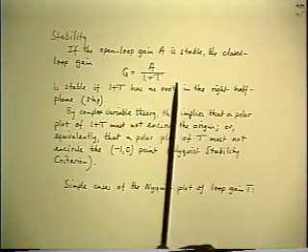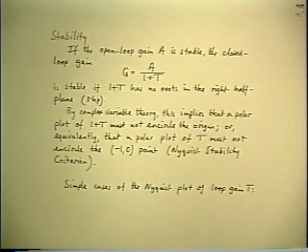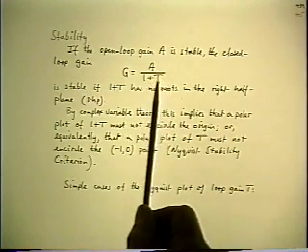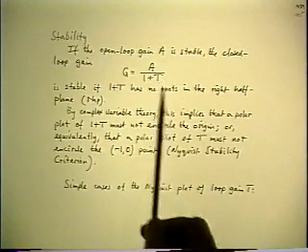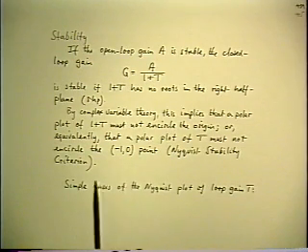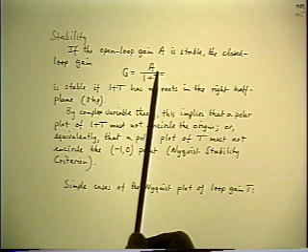So let's take the simple case where we assume that the open loop amplifier is stable. That is, all of the poles of A are in the left half plane. They're all of the form 1 plus s. Notice we adopt that as a restriction. It's not necessarily true. It is possible to have an open loop unstable amplifier and yet stabilize it when you close a loop around it. But that's a pretty tricky thing to do. So let's not get involved with that esoteric case. So let's make the usual simplifying assumption that the open loop amplifier itself is stable.